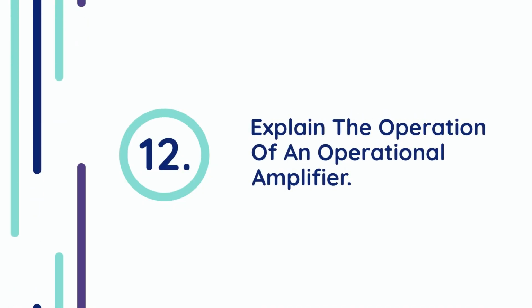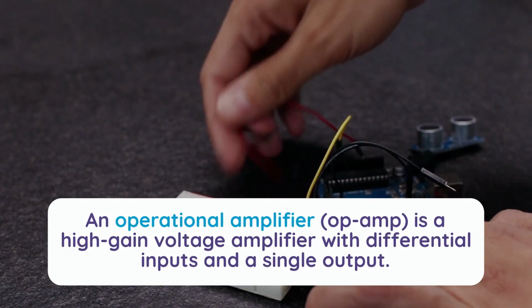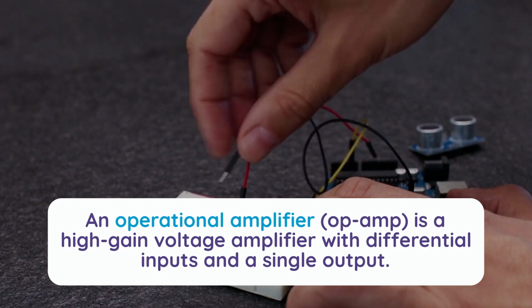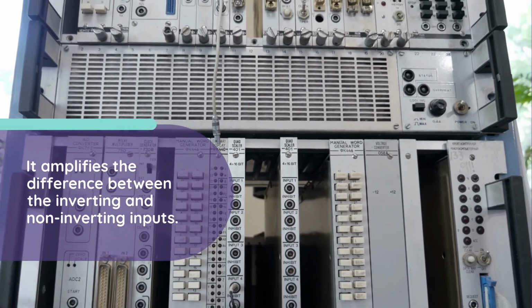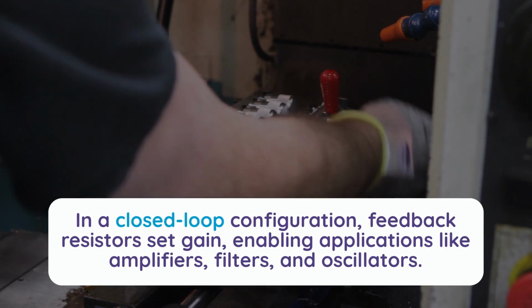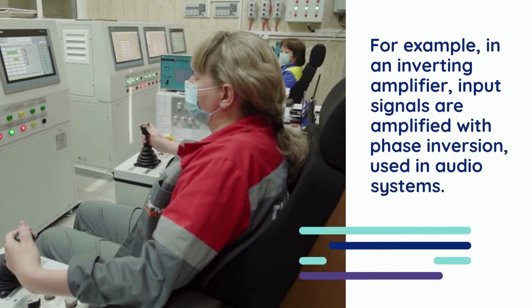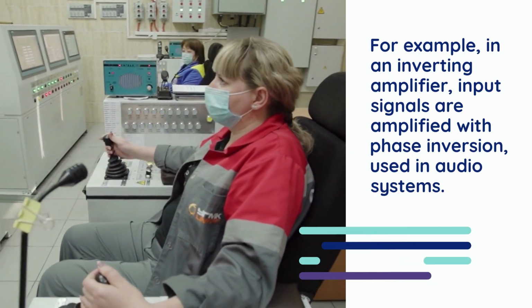12. Explain the operation of an operational amplifier. An operational amplifier, op-amp, is a high-gain voltage amplifier with differential inputs and a single output. It amplifies the difference between the inverting and non-inverting inputs. In a closed-loop configuration, feedback resistors set gain, enabling applications like amplifiers, filters, and oscillators. For example, in an inverting amplifier, input signals are amplified with phase inversion, used in audio systems.